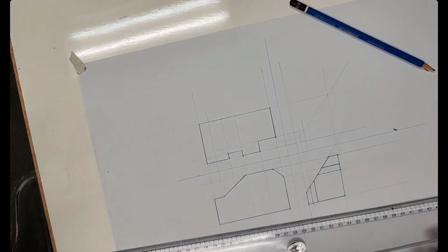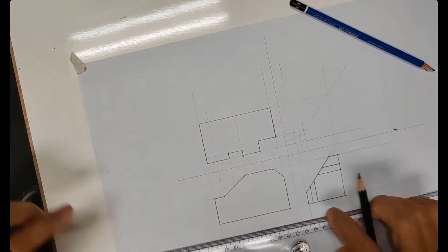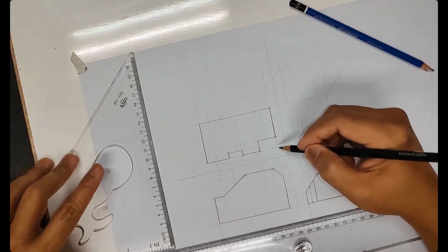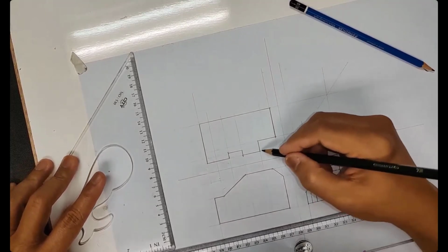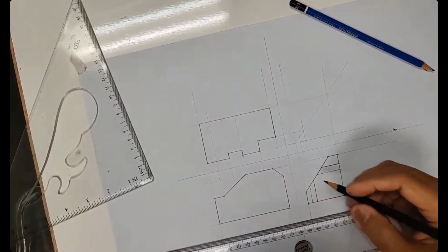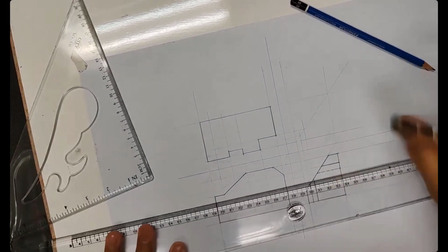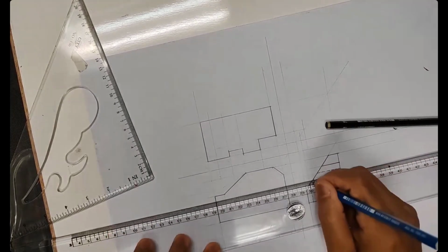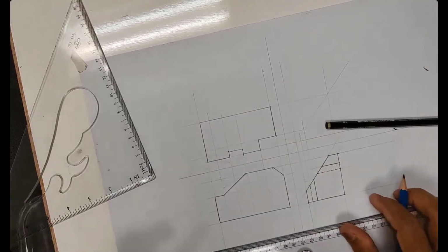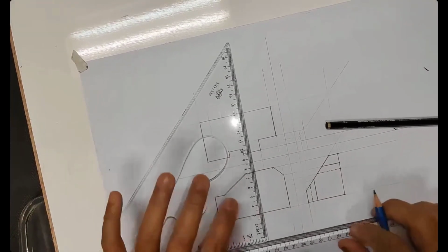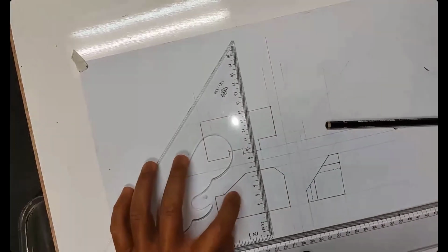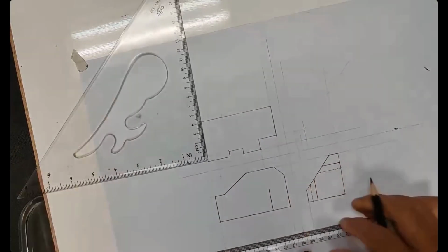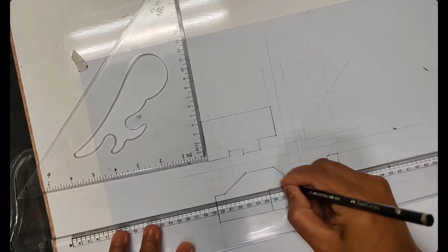Now we go further on. Here on the front view, how does this slot look? Can you see this is a slot of depth 10? So depth 10 by 10 by 20. Can you see on the side view, I already have the extension line to draw the profile. Using my 4H, this is the depth of 10, so this will be an extension line. Clearly, I have an extension line like that, here and there. So this will be the profile on the front view.